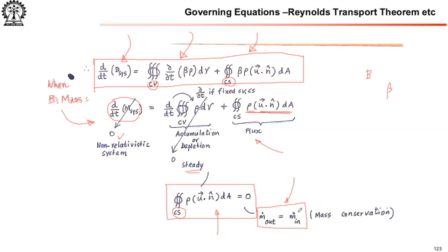Keep in mind that sometimes we choose control volumes and control surfaces intelligently. This is a descriptive thing to say, but if you have to really work out some numbers, evaluating this surface integral can be tricky, because you have to know what this u vector and this n vector are at each and every location of the control volume.